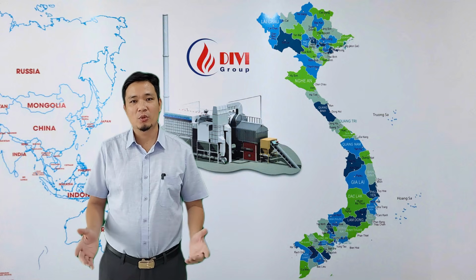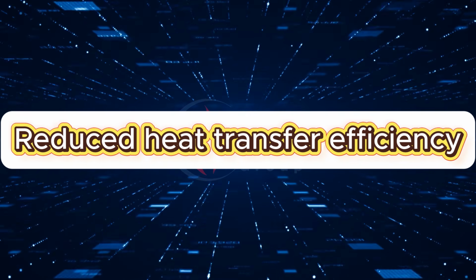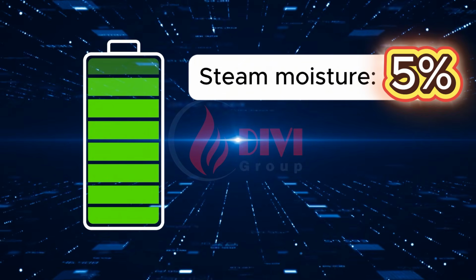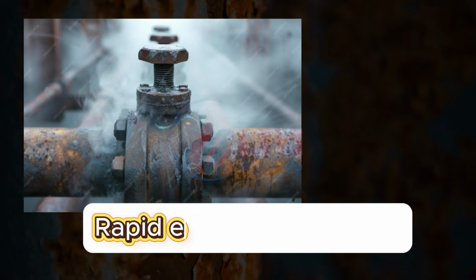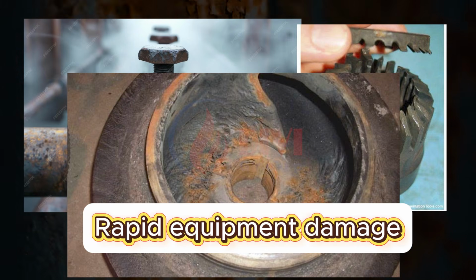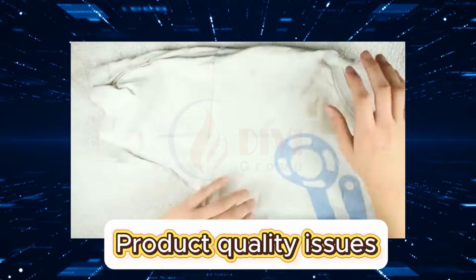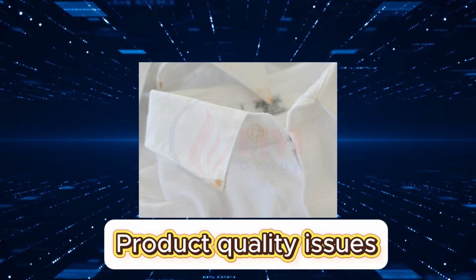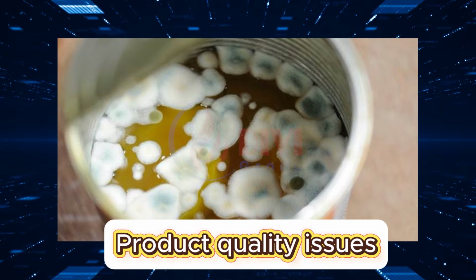So what happens if your boiler is delivering wet steam? First, reduced heat transfer efficiency. If the steam contains 5% moisture, about 3.7% of its energy is lost. Second, equipment wears out quickly. The tiny water droplets will damage the equipment. Third, product quality issues. In the textile industry, it causes fabric stains during ironing. In food processing, it may carry impurities that compromise product quality.